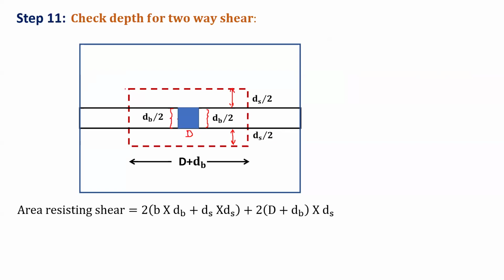So now the depth available in this portion is the depth of slab. I will write here depth of slab, here depth of slab, and in this portion depth of beam. So how will we get them? We have two times on this side and this side, both sides. So we have ds plus ds by 2, so this total becomes ds, and depth available over there also ds.